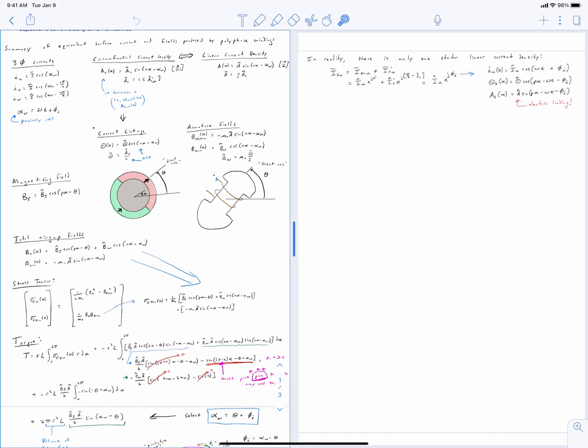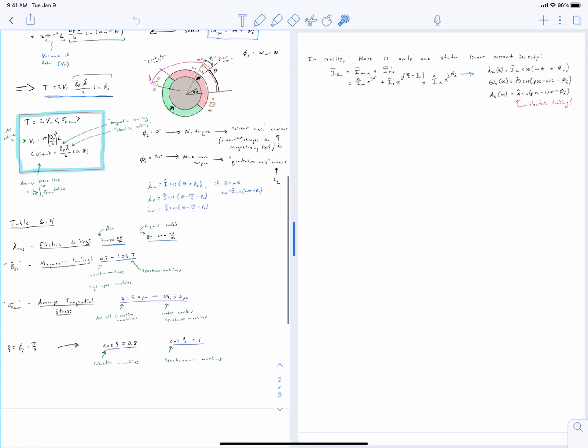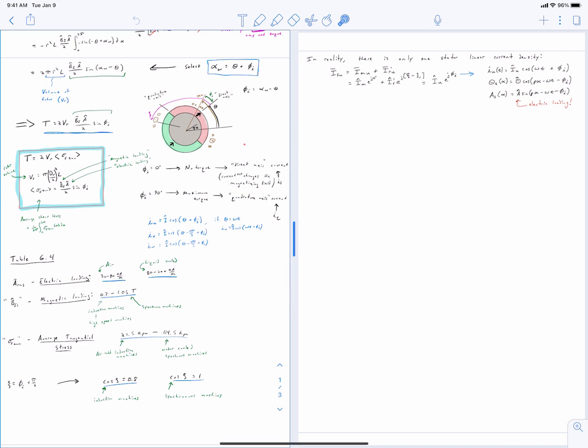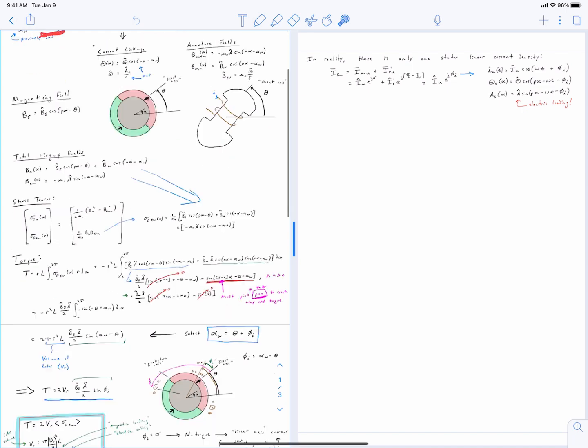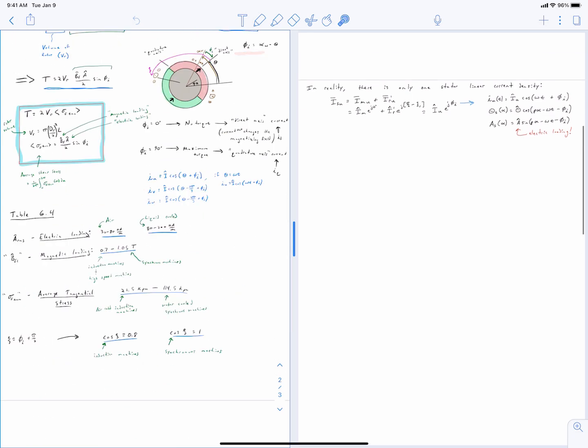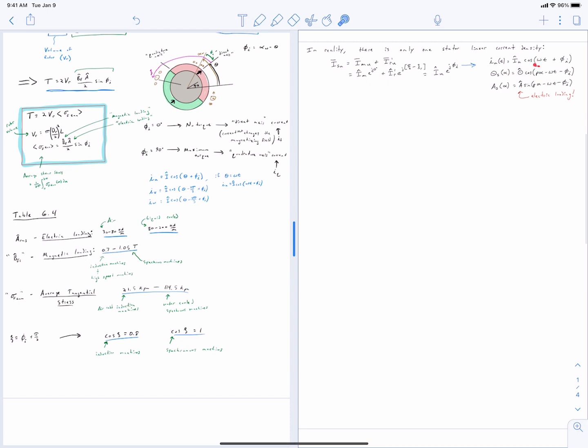Now, furthermore, going over to the AC machine design sizing video, we drew this cross section of our machine at that point, and we had our magnetizing field located at theta equals omega t from horizontal, and then it had this angle phi I, which was the same angle that we had in our currents. So that phi I is the phi I up here, and this phi I is now appearing in our new notes as well.